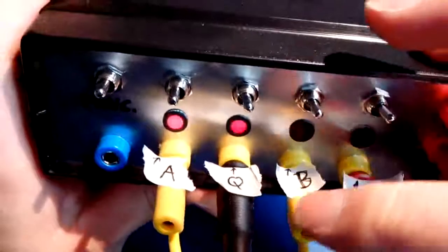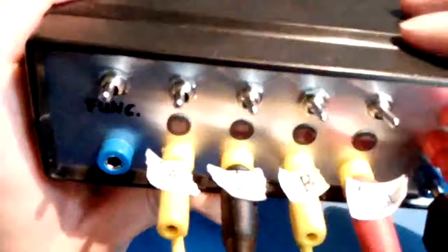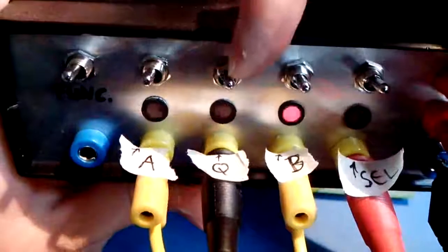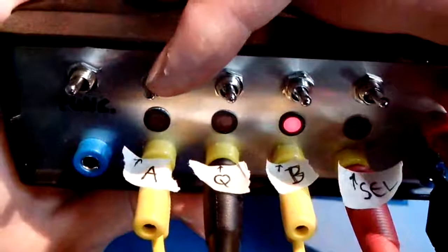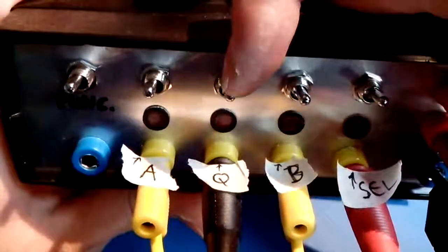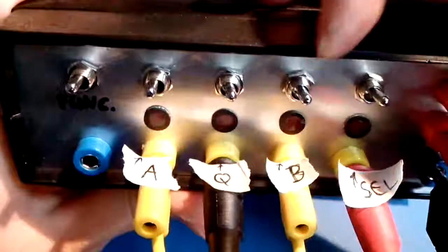The output of the multiplexer can be visualized like this. So now we have the select input, we have input B, input A, and the output of the multiplexer. And as you can see, since the select input is 0, input A is selected. So the output Q follows input A, right? The middle LED, the LED for Q, follows the LED of A.